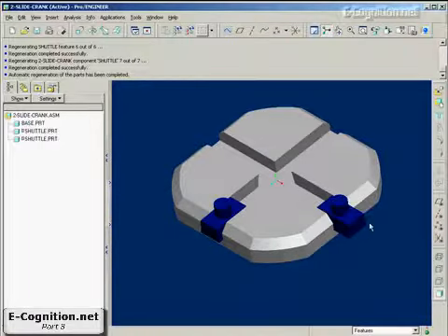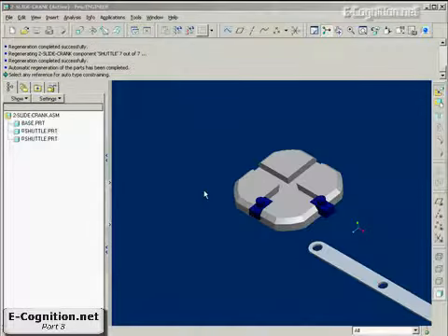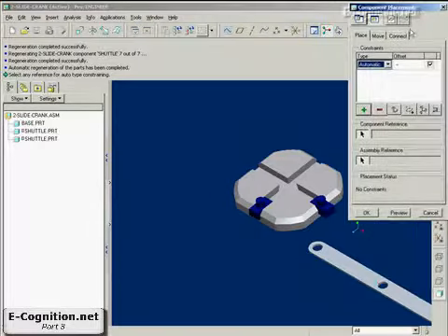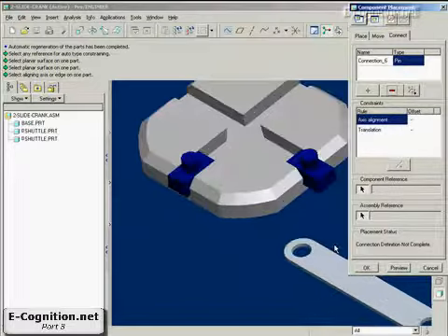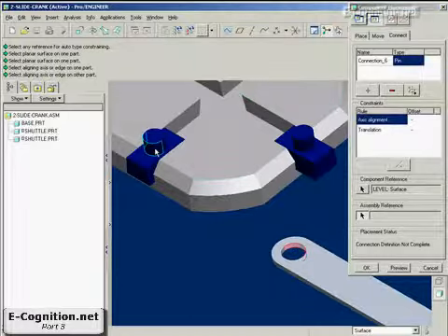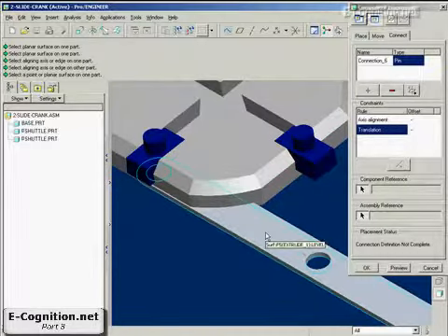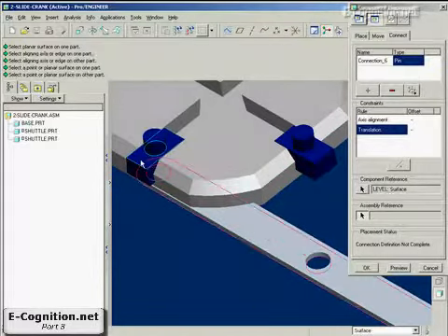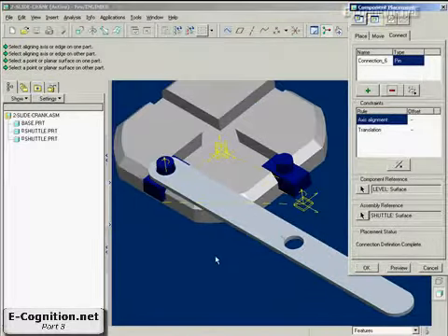Alright, well, let's go ahead and add then the lever. Gotta change that too. Now we're going to add also as a connection, but this time we're going to add a pin to the first connection, where the axis alignment is going to be with this cylindrical face and then the cylindrical face on the shuttle. And then the translational aspect of the pin joint is going to be the bottom face of the lever and the top face of the shuttle. And there's our joint, already fully defined.